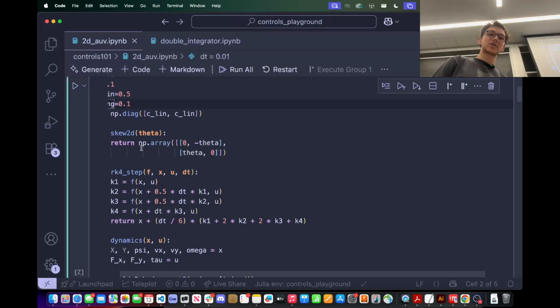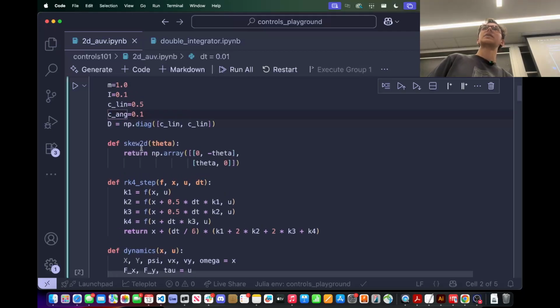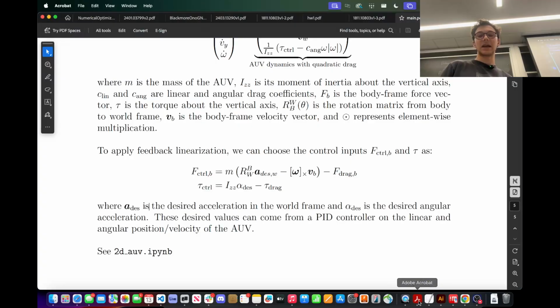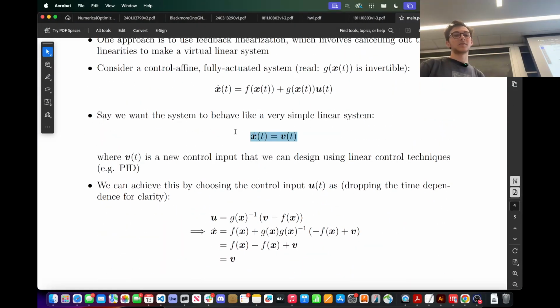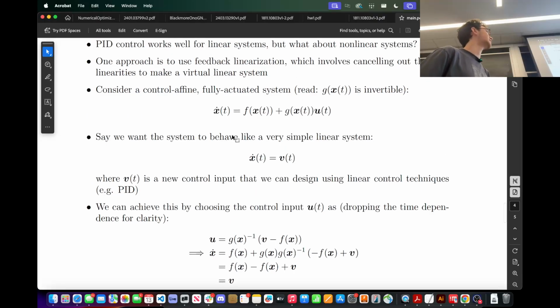But in terms of actual control of the vehicle, because it's fully actuated, we get these really nice feedback linearization type controllers that make the control of the vehicle actually pretty simple. I should note, if you have a non-fully actuated system, you cannot do full feedback linearization. So you can't do what we just did here, because I'm just not going to be able to produce something like this, which is the crux of what we're trying to do here.